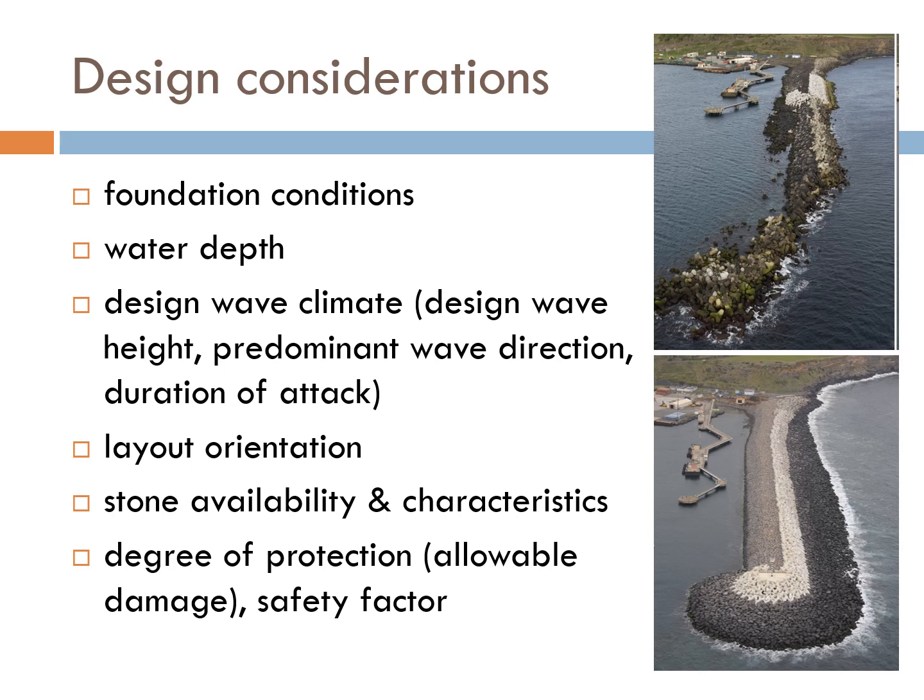As we mentioned, rubble mound structure will be subjected to damage. If it is desired that the structure has minimal damage even under the most severe condition, then the armor unit required will be relatively large and thus much more expensive.